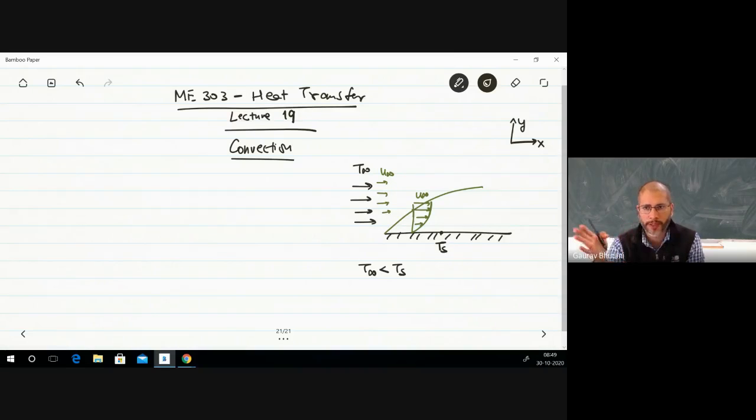Since they are moving, they take away the heat and allow fresh cold molecules to replace them, which again get hit by the lower layer. There's no layer as such which is not moving, but we are discussing in the sense of layers. The molecules just above the surface hit that cold layer again, which becomes hot, and then they move on. So this is how you have convection happening in this situation. This is the mechanism.